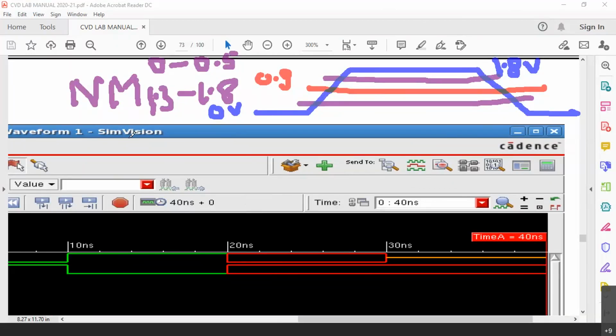In all digital logic, it has to be 0 or 1, right? Unlike in analog, where we can have infinite values in between, in digital we should have two distinct values. So we have to define this noise margin in this manner. It is we designers, based on our own system specifications or requirements, who define our noise margin. And if we define it this way, what about between 0.5 and 1.3? Still it can be 0, still it can be 1, we don't know. But how do we define it?